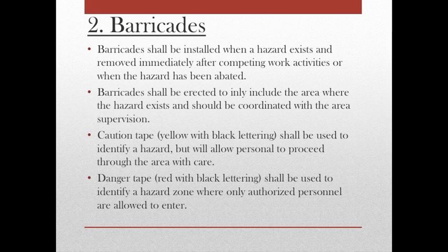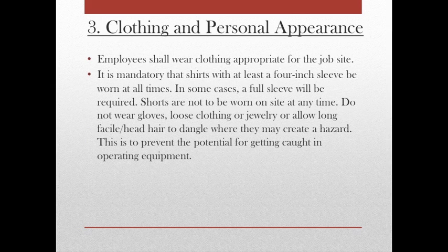Barricades. Barricades shall be installed when a hazard exists and removed immediately after completing work activities or when the hazard has been abated. Barricades shall be erected to only include the area where the hazard exists and should be coordinated with the area supervision. Caution tape, yellow with black lettering, shall be used to identify a hazard, but will allow personnel to proceed through the area with care. Danger tape, red with black lettering, shall be used to identify a hazard zone where only authorized personnel are allowed to enter.